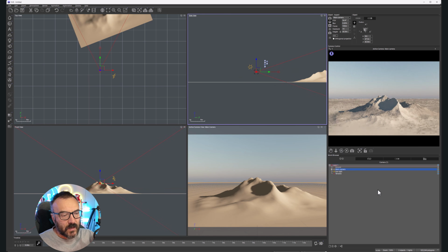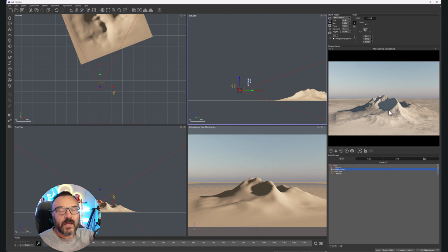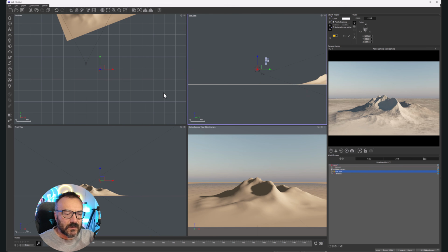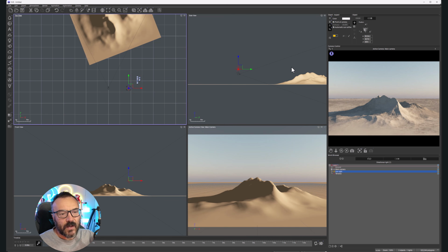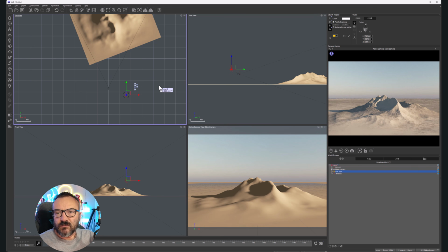Okay, we'll take our main camera. Also, the lighting is very important. We are working with three-dimensional objects, but we are working in a two-dimensional representation because our screens are flat. The lights, shadows, and highlights are what deliver the shape of the object to us. We can modify this by selecting sunlight and moving it a little bit left, right, up, and down. We can find the perfect position to make sure the light gives us a better and more interesting shape in this case. And I think this works just great.